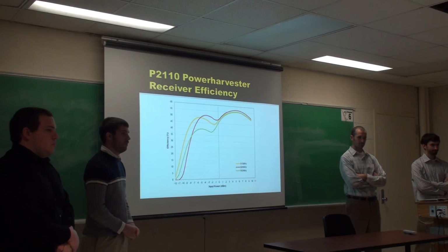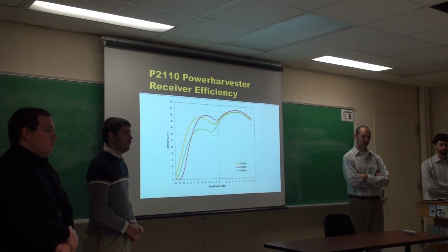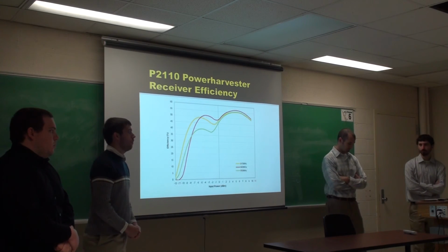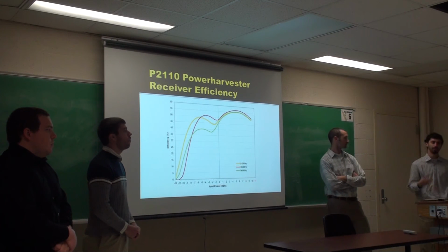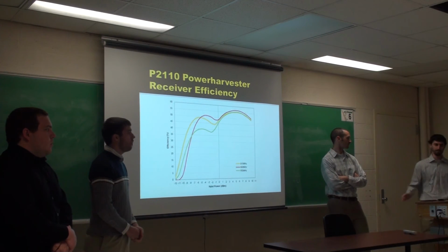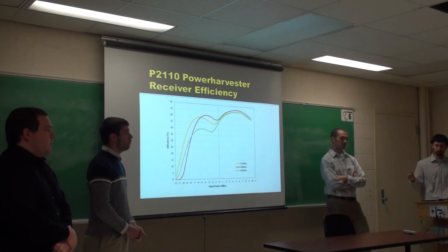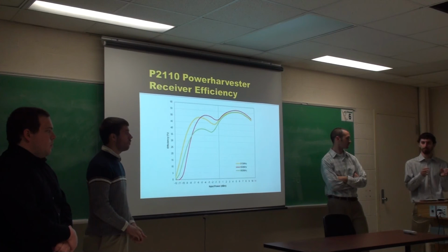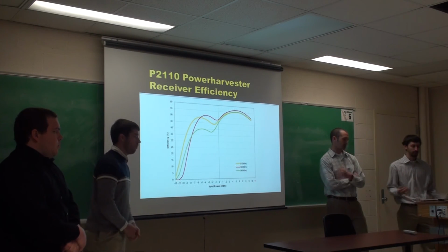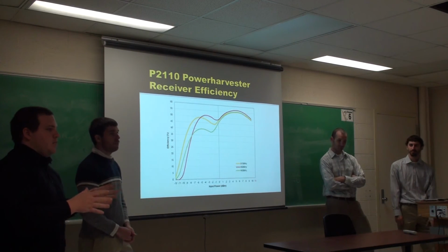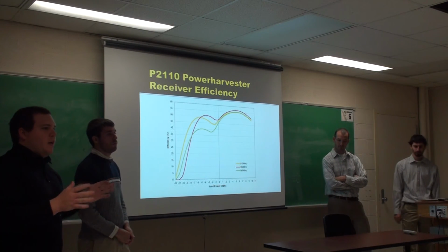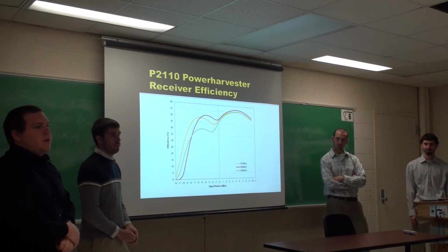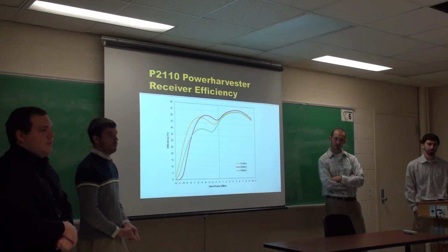What do you see as the limitations of using RF? Definitely the range. The range is a big factor. We were just testing in the lab, and the packet frequency just varied. It drops dramatically if you just put them far away. I think it's because we didn't have our transmitter placed correctly, which is another weakness. Our transmitter is not pointed in that 120-degree angle. Your nodes are not going to be. The directionality is not. Yeah.